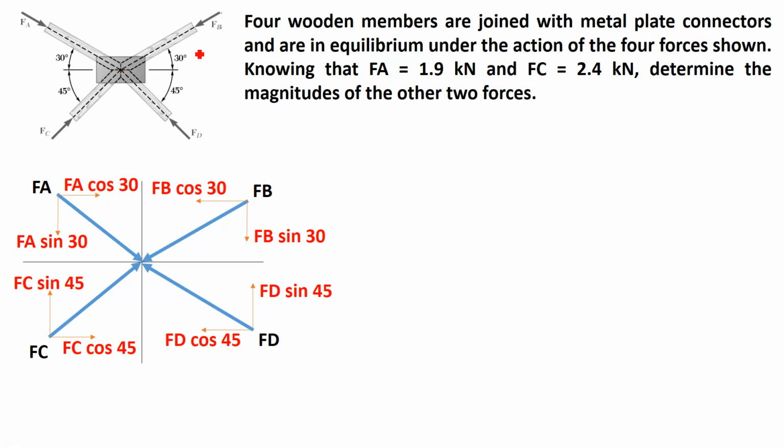If you look at the figure carefully, all four forces are push type of force, right? So it means Fa, which is given in the second quadrant, since it is a push type, actually the force is going in the fourth quadrant. Similarly Fb, which is shown in the first quadrant, is going in the third quadrant.